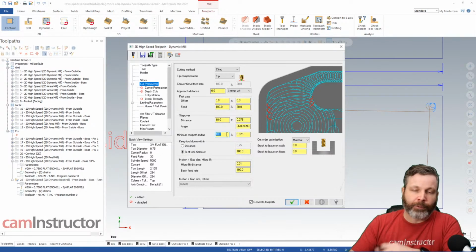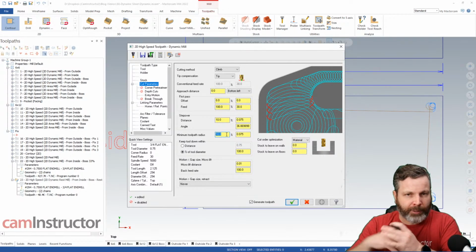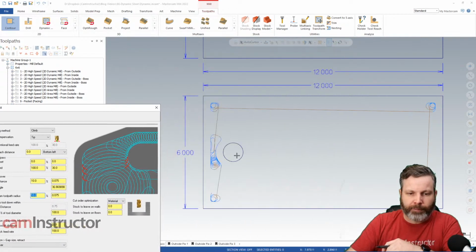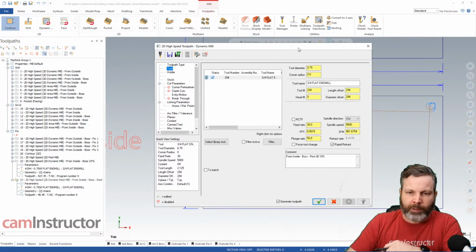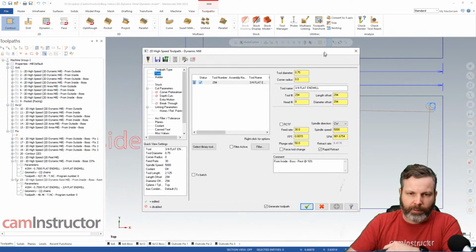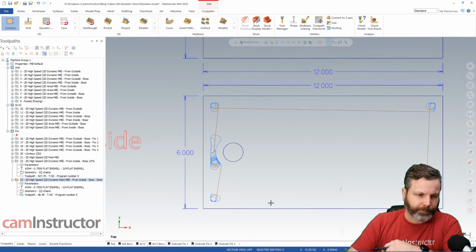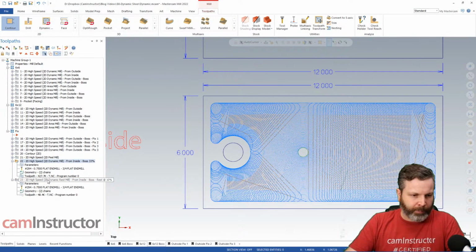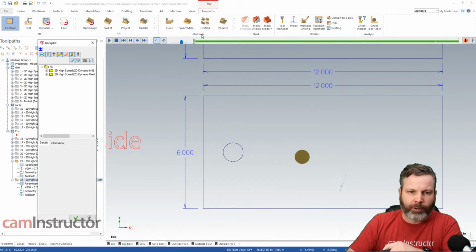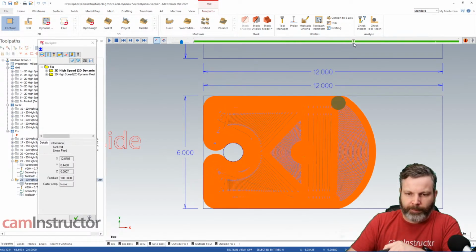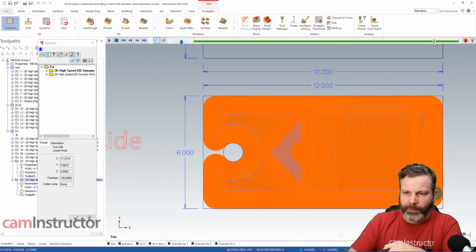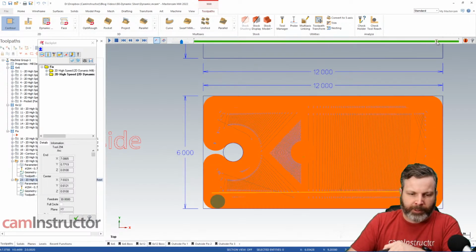And then I've set that minimum toolpath radius back down to fit so that it does fit up into here. Okay. So this will make tool motion only in the uncut sections at the reduced feed rate. Okay, so we get these two tool paths, and we can run through them both. So here is the reduced arc toolpath, or reduced min radius. And this is our second toolpath that now comes in and just finally nibbles away at those corners at the reduced feed rate.